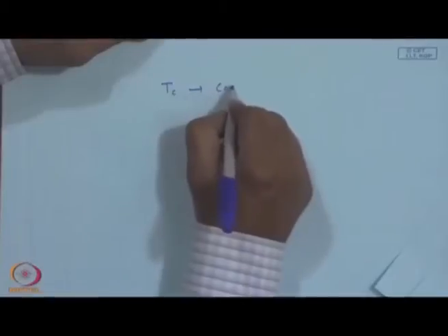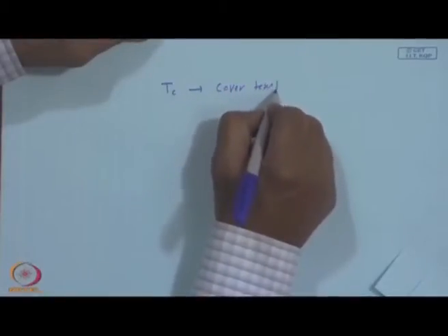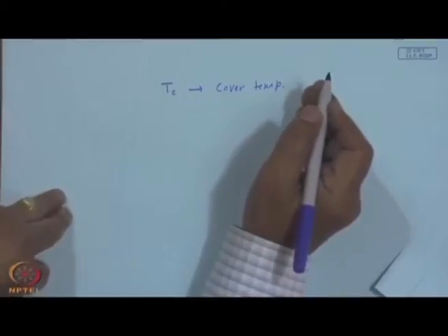And there is no absorption of solar energy by covers in so far as it affects the losses. So, if T_c is the cover temperature, it is a result of whatever convection is taking place from another cover or the plate and not necessarily the absorbed energy. In other words, we will consider the solar radiation to be transmitted through the glass cover or reflected and not absorbed. The temperature increase is not due to absorption, but by a convective heat exchange only.